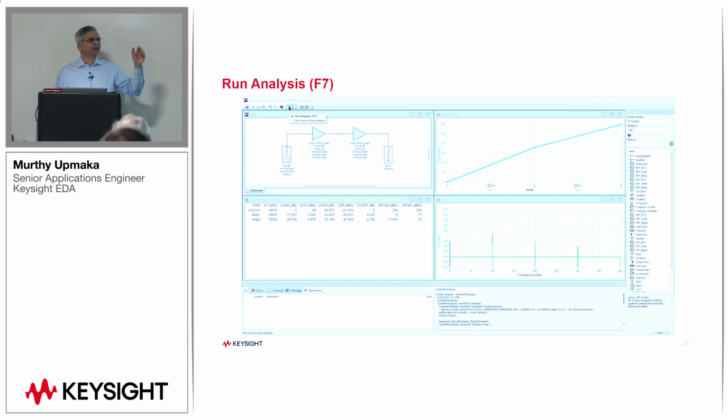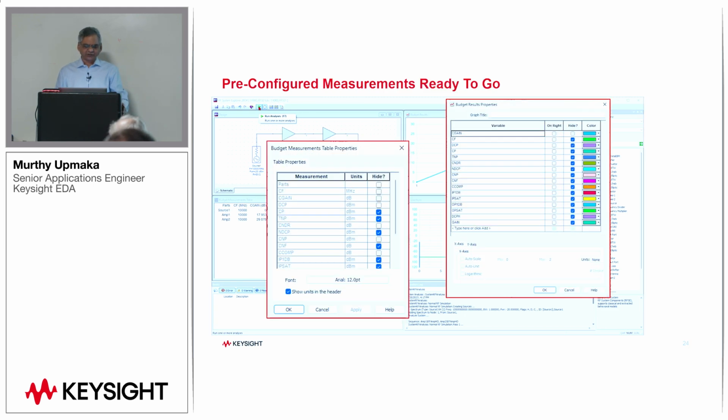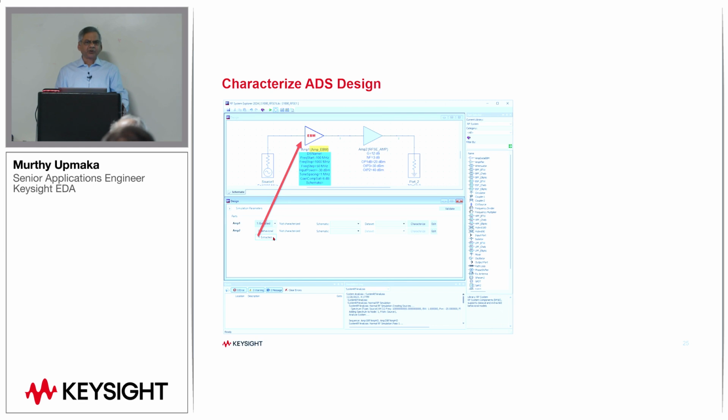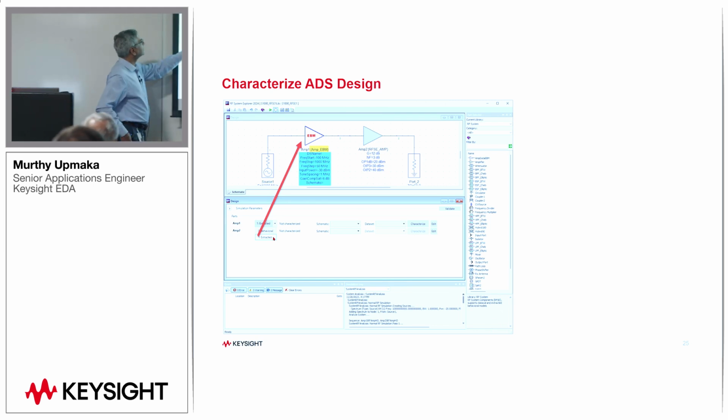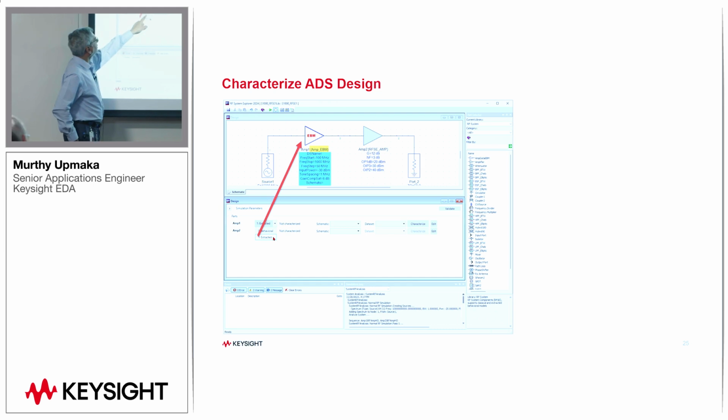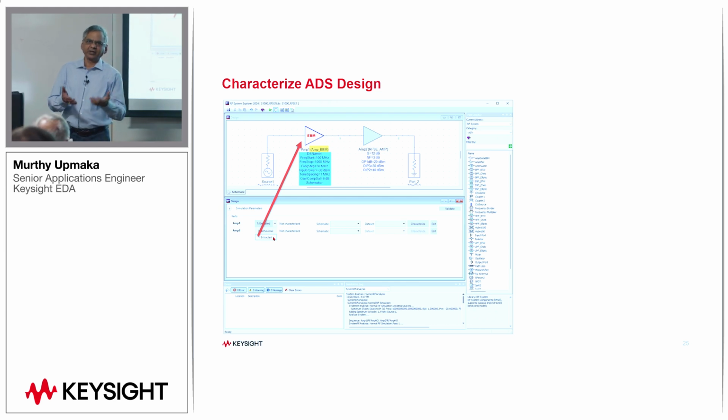So let us say you have put 2 amplifiers together, and then you are looking at the spectrum, and the level diagrams and things like the cascaded gain, etc. And you want to then substitute your circuit. So what happens is in the UI, instead of behavioral, sorry, this is a small text, here it says behavioral, you can designate it to be extracted.